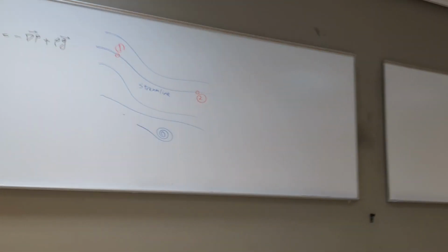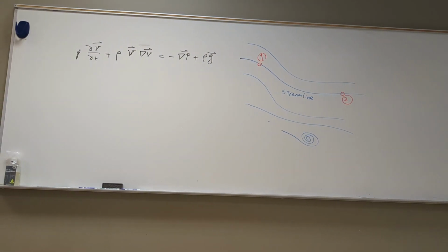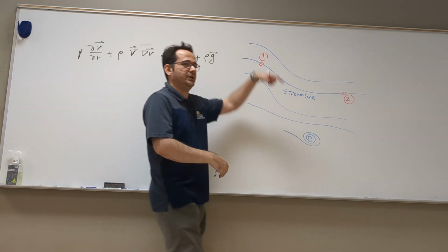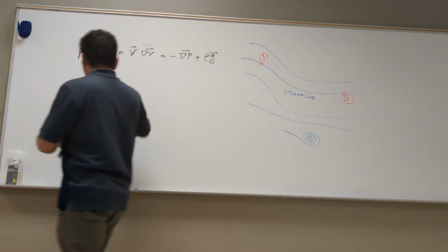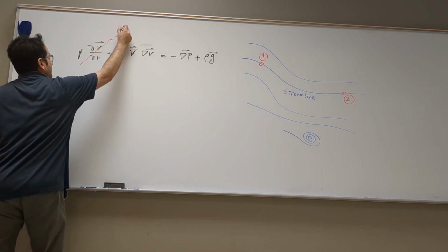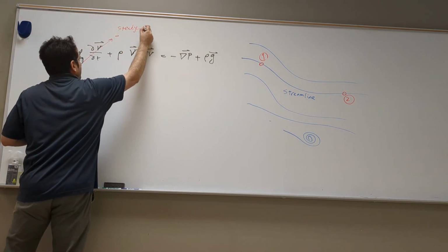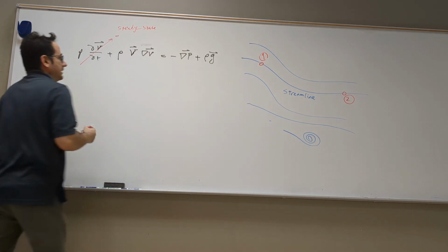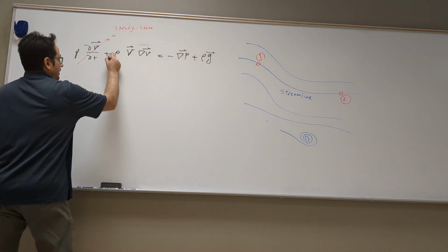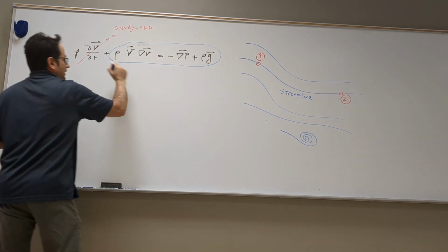In a real unsteady flow, nothing stays constant. But you can always find, like in machinery, like pumps, that after some period of time the transient effect will diminish, and then you have a steady state. That means this streamline is not fluctuating. In that case, any time derivative for a steady state is 0. Therefore, your equation is that: rho v grad v is equal to that.